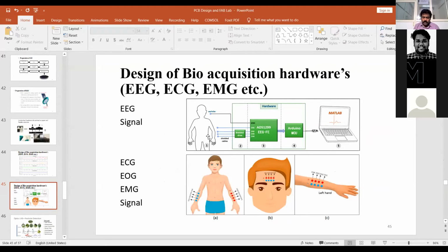So this is one of the hardware you can make, even with flexible or non-flexible ICs, and especially for biomedical study. This is very useful. Now, the ADS1299 is not an ideal microcontroller. This is an ADC module. We have 8 channel and 16 channel models.